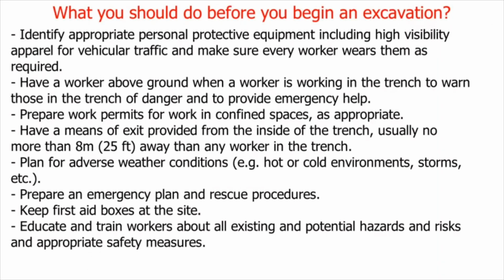Identify appropriate personal protective equipment, including high-visibility apparel for vehicular traffic, and make sure every worker wears them as required. Have a worker above ground when a worker is working in the trench to warn those in the trench of danger and to provide emergency help. Prepare work permits for work in confined spaces, as appropriate.